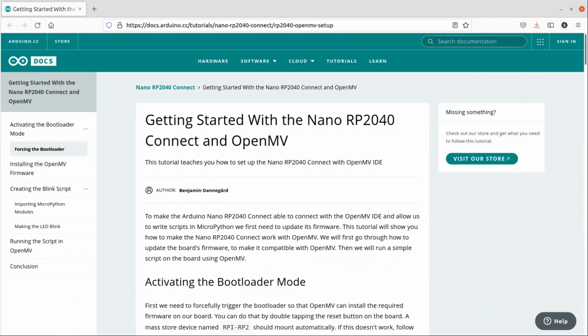I'm going to look at 2 ways of running MicroPython on the Arduino RP2040. The official Arduino way, as well as how you could use the standard MicroPython version using Thonny or using minicom and the command line. Both will work for the example I'm using. The first is based around the OpenMV fork of MicroPython, whereas the later example will use the upstream version directly from micropython.org.